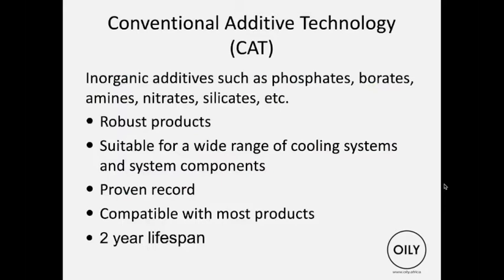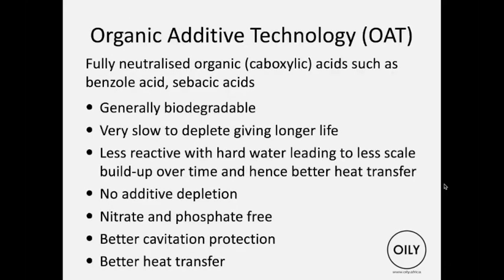The conventional additive technology is inorganic additives such as phosphates, borates, amines, silicates, etc. They're robust. They've been around for a long time, but they've got a maximum lifespan of 2 years. And they're compatible with most parts of the engine. So that's your typical green one.